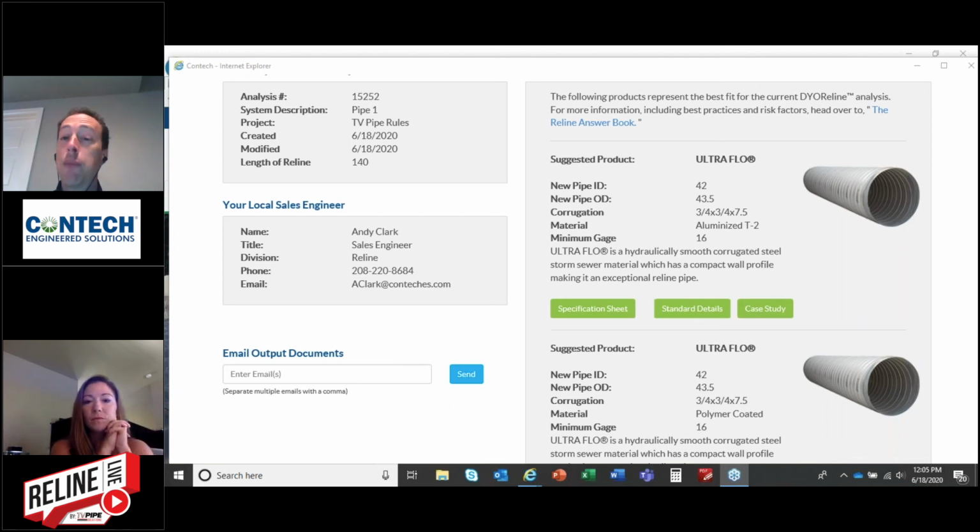Good question. So type of grout is a big concern. Keep in mind, I was just throwing numbers out there just to provide an example, but that would be enough space. Type of grout, and in this case, a lot of people like to use grout tubes from the bulkhead, from the inlet or the outlet end. They likely wouldn't fit in this case, so we would need grout ports, and those would be pre-installed at our plant, where you can inject and review the grout as it's being installed, so you know what height it's at and everything else. So good question.